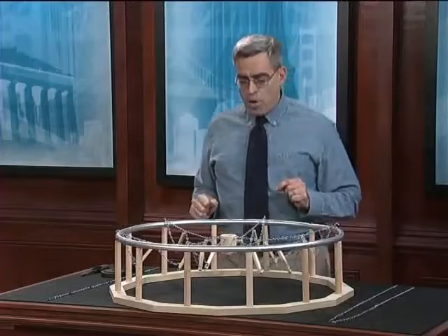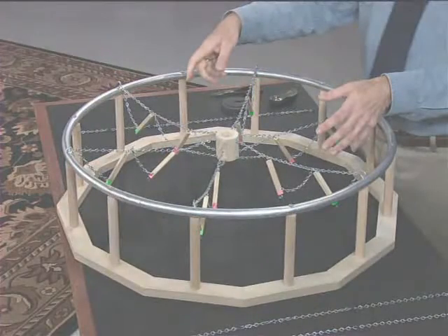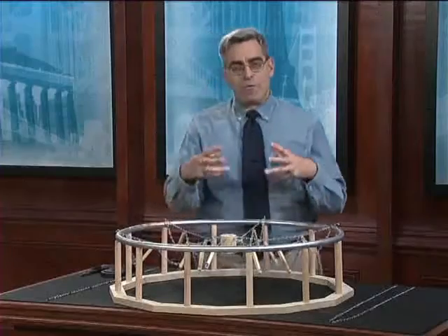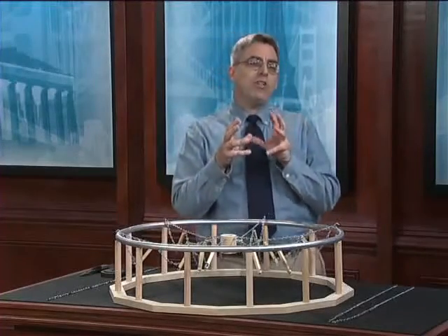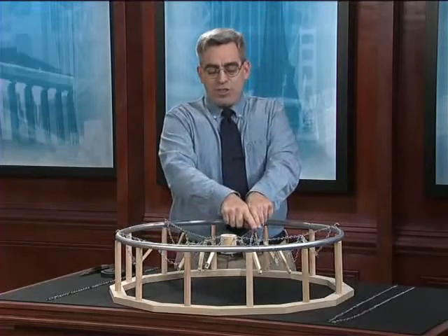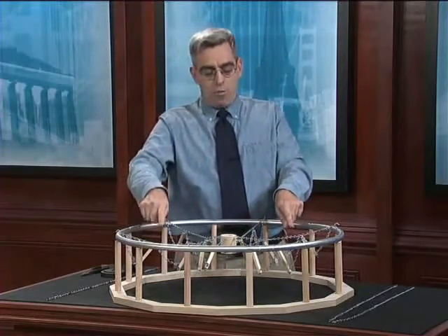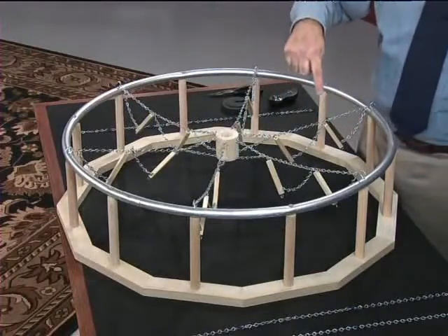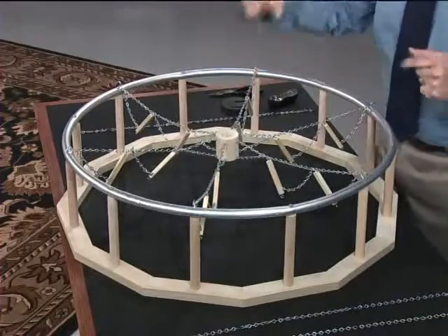Now the next step will be to connect together the bottoms of those struts. We could create something very similar to the Utica auditorium roof by simply adding a tension tie from the bottom of each of these compression struts across the dome. However, what David Geiger saw was that there was a much more interesting way to accomplish the same thing. Rather than establishing a tension tie directly across the bottom of the dome, he realized he could get the same effect by adding a circumferential cable that goes around the circle instead of across the circle.